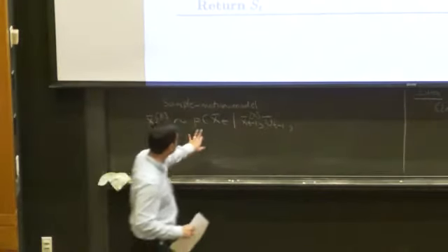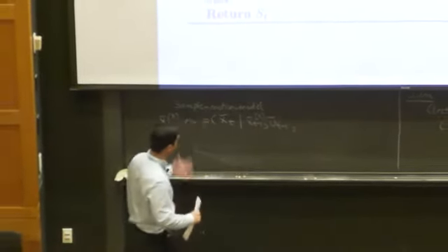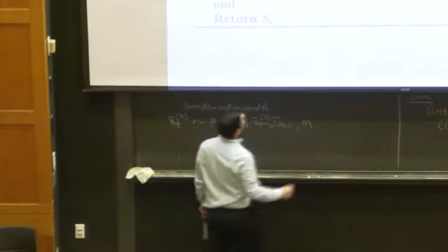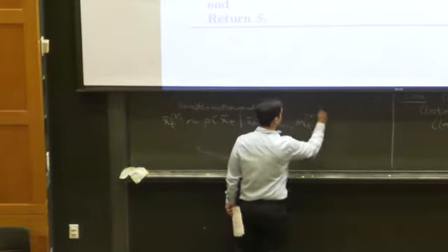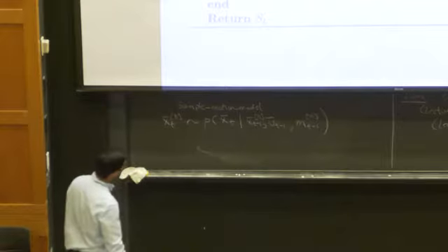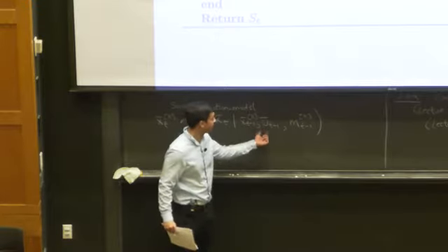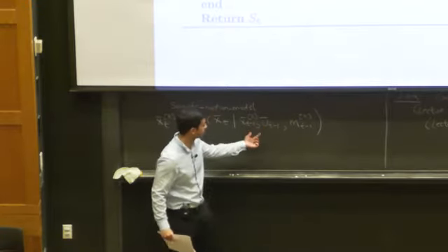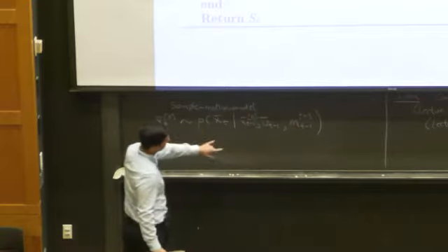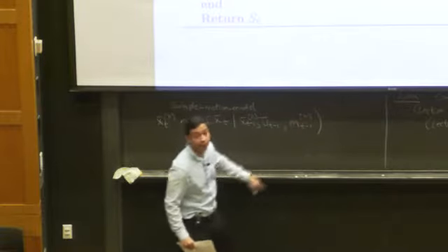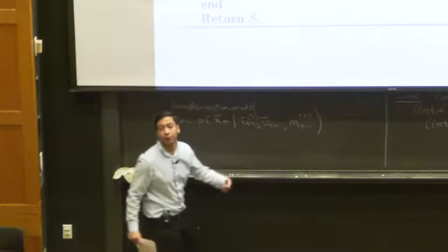All right, so we're sampling x_t^k from this conditional distribution. So this is our dynamics model, and then there's a map m_{t-1}^k. Given a location or a state at the previous time step, given the control input that the robot took, which it knows, and given some estimate of the map as captured by particle k, we're sampling some possible next state for the robot.